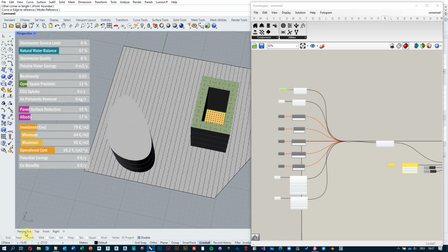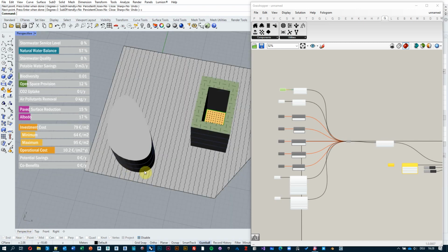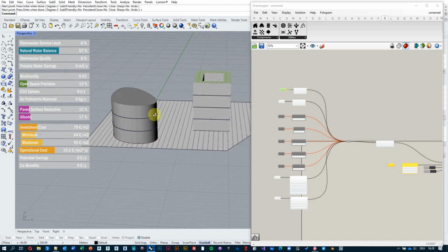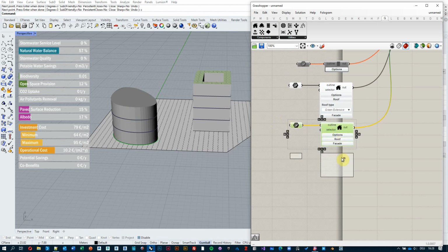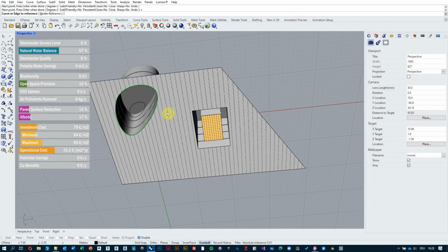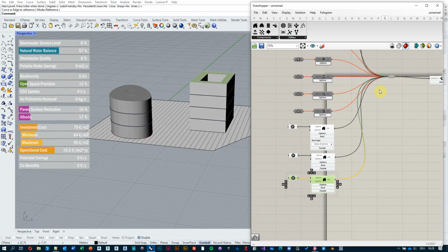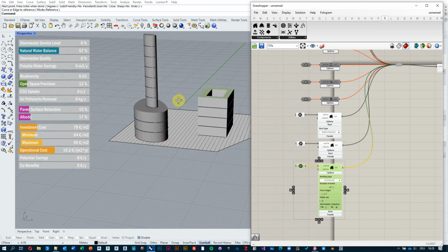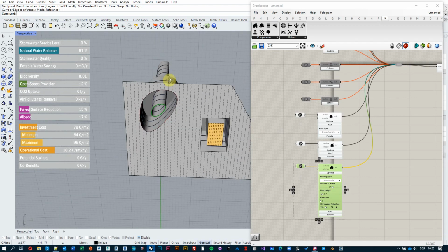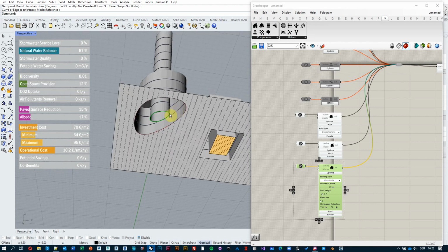If we wanted to, for example, again looking from the top view, it's easier to draw, introduce a tower that is higher than these 3 floors over here, this is the base for our tower. Then how we would construct it is we would create yet another building component, set this curve to be part of the building, and then add it over here. And right now nothing really happens because they are of the same height. But if we add more stories to it, you could see that it's coming up over here. So our building would be constructed like this.